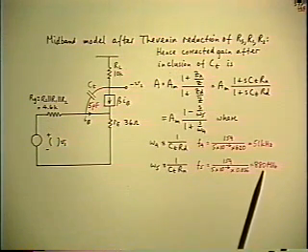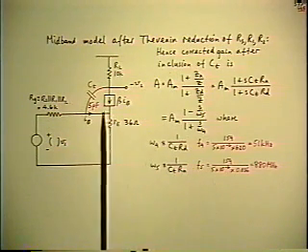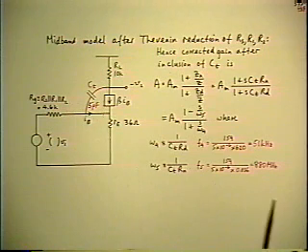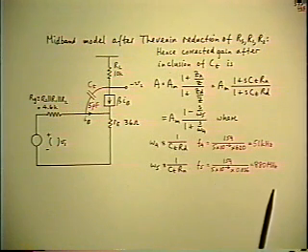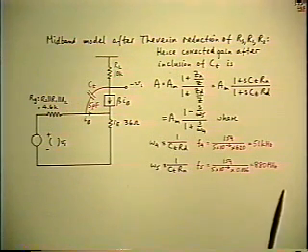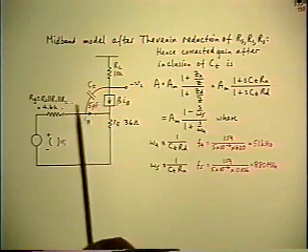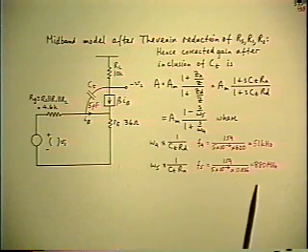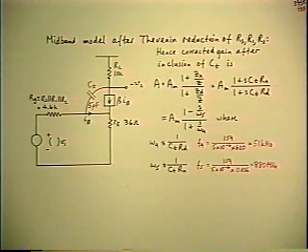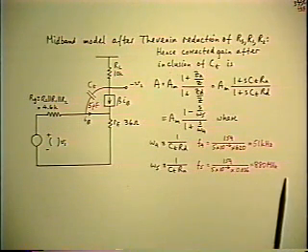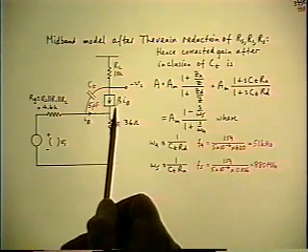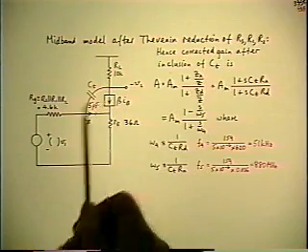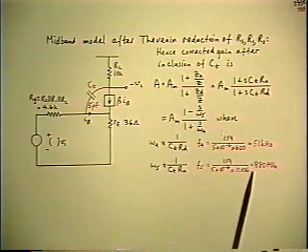You haven't noticed it because lots of other things have fallen apart before you get to this kind of frequency. In other words, the model is no longer adequate to explain what really goes on at frequencies like that, and you don't care anyway, mostly. So, because of the numbers, you may not have noticed the fact that the right half plane zero exists.